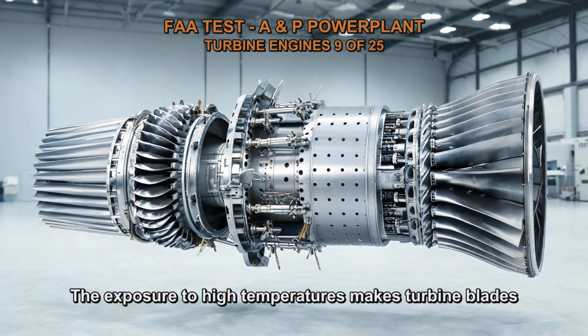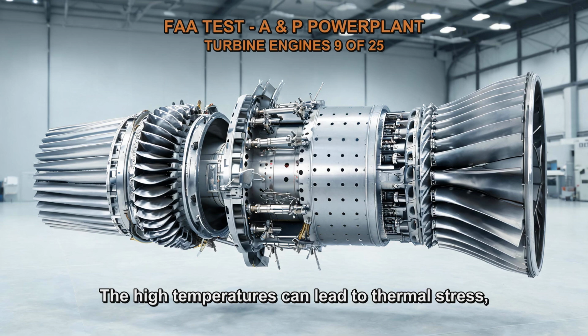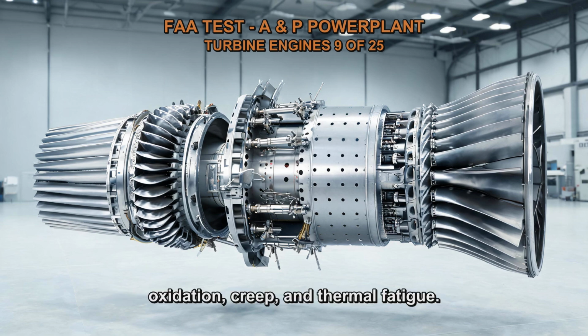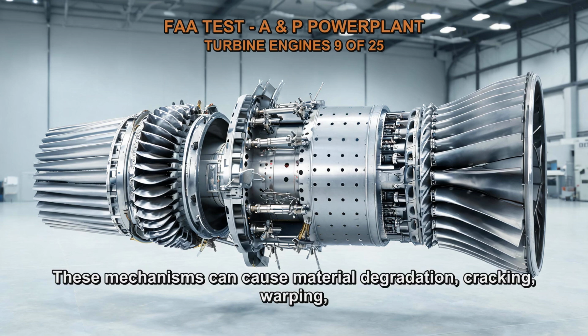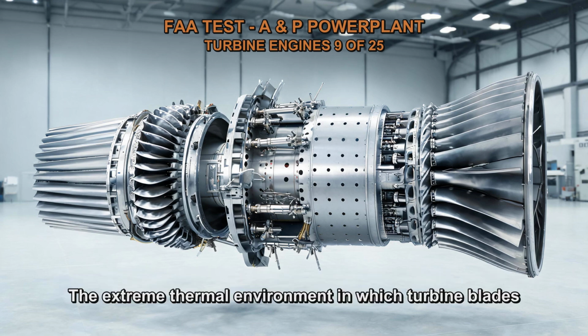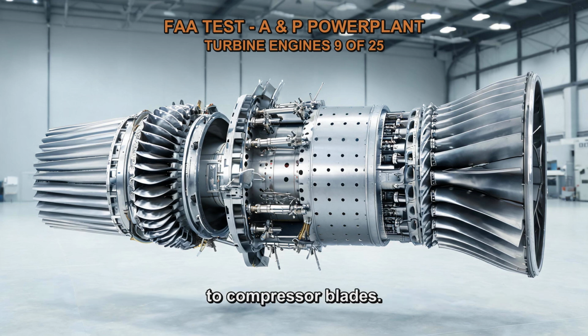The exposure to high temperatures makes turbine blades more susceptible to various forms of operating damage. The high temperatures can lead to thermal stress, oxidation, creep, and thermal fatigue. These mechanisms can cause material degradation, cracking, warping, and other forms of damage over time. The extreme thermal environment in which turbine blades operate increases the likelihood of operating damage compared to compressor blades.